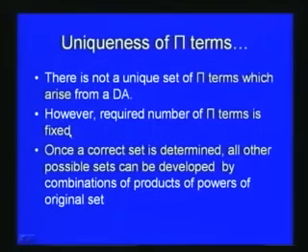However, the required number of pi terms is fixed. In the analysis, the basic steps we have seen earlier, the number of pi terms is fixed. So there is not a unique set of pi terms coming from the dimensional analysis. Once the correct set is determined, all other possible sets can be developed by a combination of products of powers of the original set.